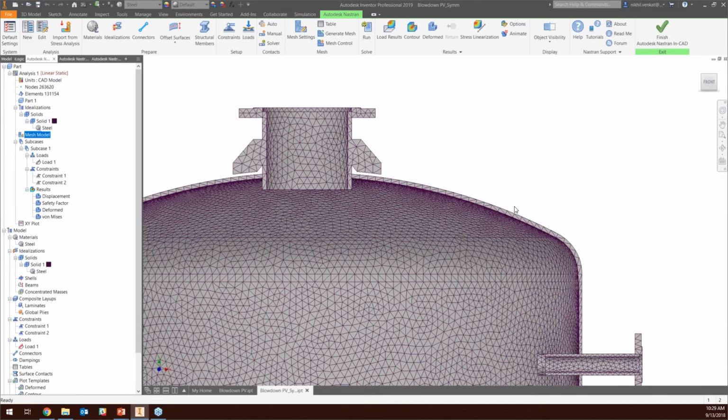So what I like to do is, when I first start doing some simulations, some design validation of my particular design, go ahead and go with maybe a more coarse element size to start out with, and just run your analysis. If you see what's expected, like, I'm going to apply a load here, and if there's a deformation in that area, sure, that's expected. But if there's a deformation somewhere completely different than what you expected, then maybe start driving the mesh finer and finer and figuring out exactly what's going on.